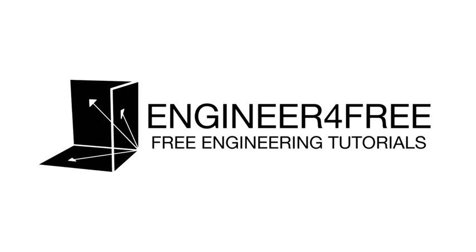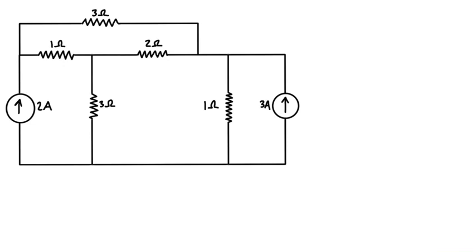Alright, welcome back. Doing another example here with nodal analysis to solve the voltage drops and current through each of these resistors. And in this case we have a circuit with two independent current sources. So the very first step that we want to do is we always want to pick a node and ground that node, and that's going to become our reference voltage, basically our zero for the rest of the problem.